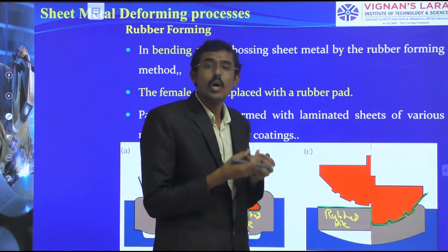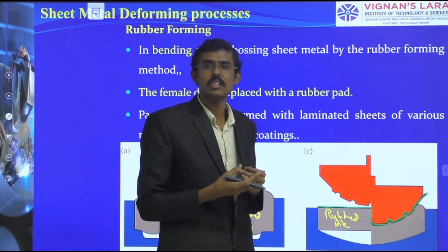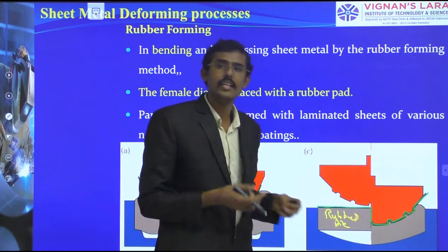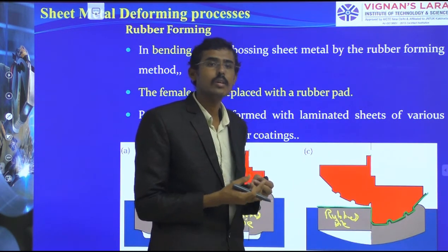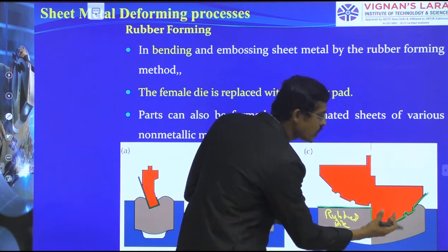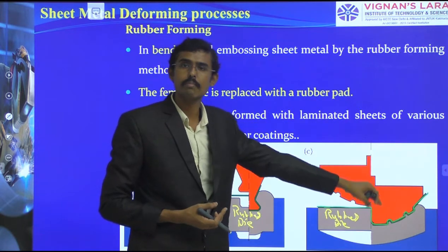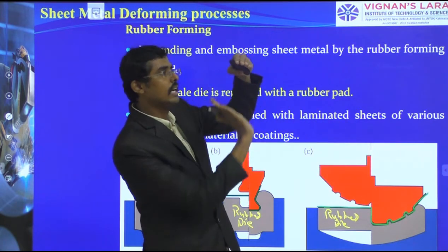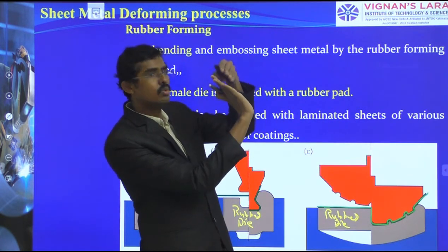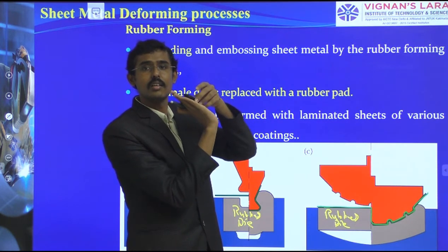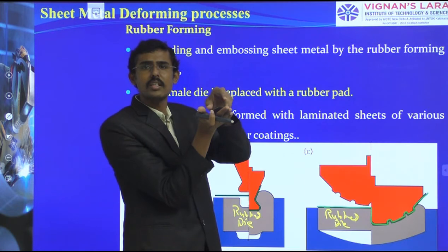But to avoid crack formation, we make some flexibility in the rubber pad, in such a way that it can lightly create a cushion effect there. Even though it has to take the impression, it has resistance from the other end, so only the impression falls on the product. But if it is very rigid, what happens?